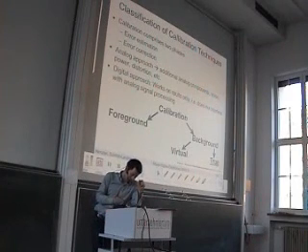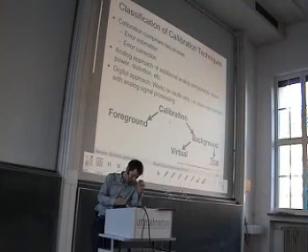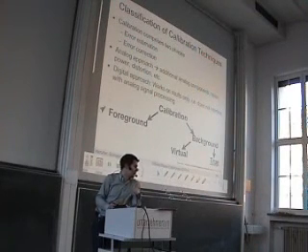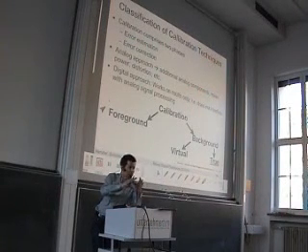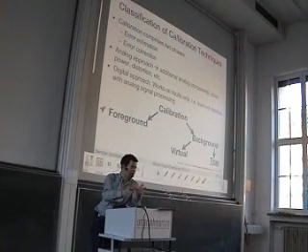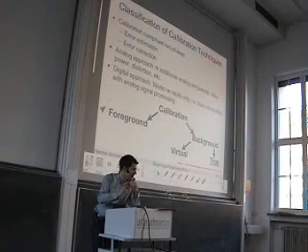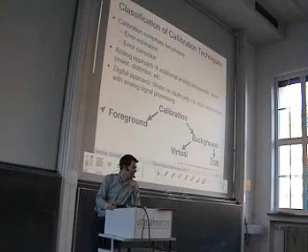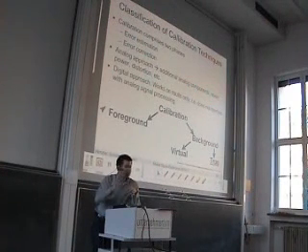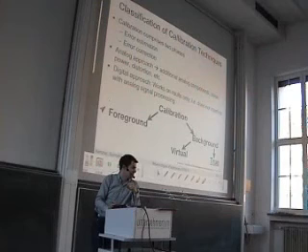Well, here on this picture you can see several classes of calibration. The easiest one is the foreground calibration. Foreground calibration means you start up your system, you know there's some problem, then you insert some test signals, measure the failure, and compensate for it. After you have done this, you turn off your test signal and have a regular mode of operation.